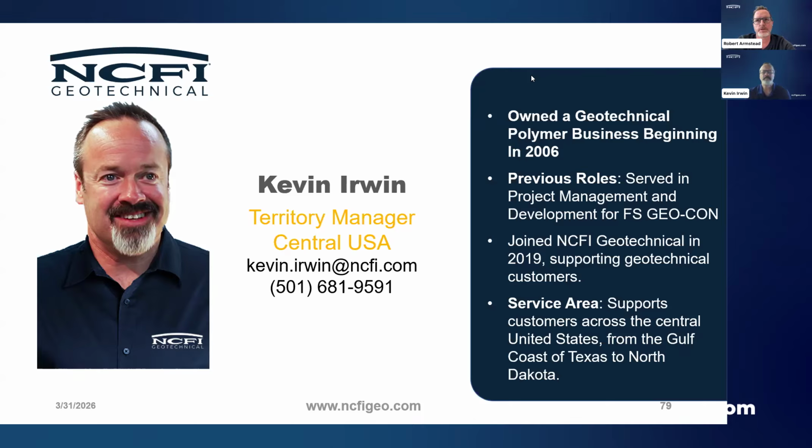Sure. And I can say there are some instances we've seen, doing culvert injections or working in areas where you've got a relatively high flow rate with groundwater or some other flow, what you can do is some shorter shots to get the material to gather on whatever structure or material you're working with. Because of that shorter shot, hopefully there's reaction. It gives it something to cling on to. Then the adjacent shots that come after will cling on to the existing material in place. So it can be done through technique, in order to get the poly to adhere and react.